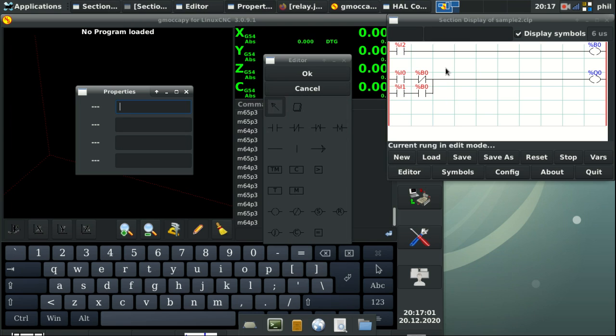The reason to do this is a couple-fold. You can utilize the same output in different scenarios. It's also good for troubleshooting to see the physical output being triggered on a separate rung. Another thing that it's good for is tying in numerous bits of safety into this circuit.